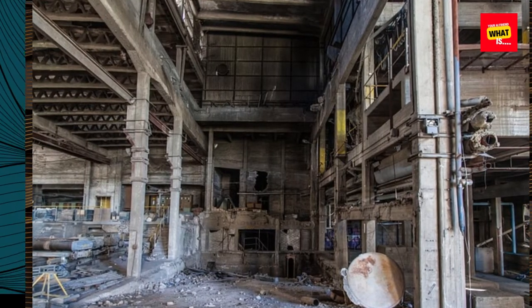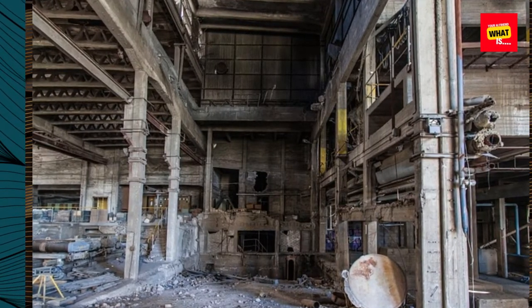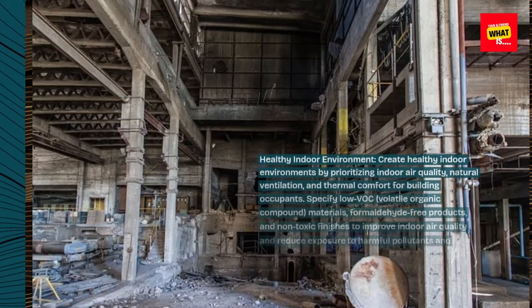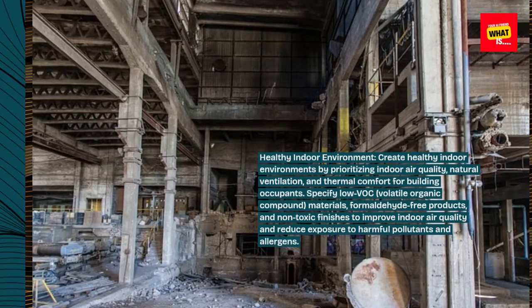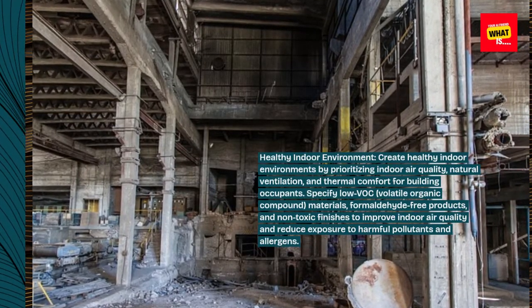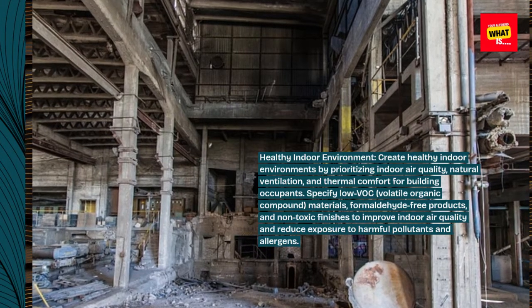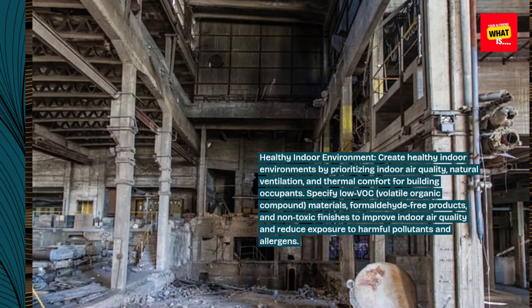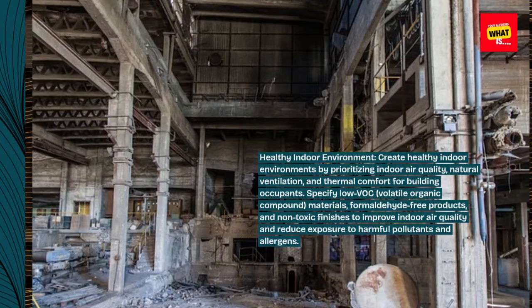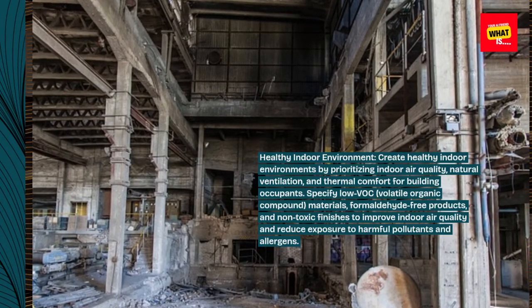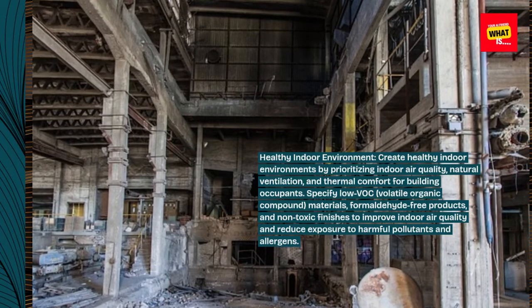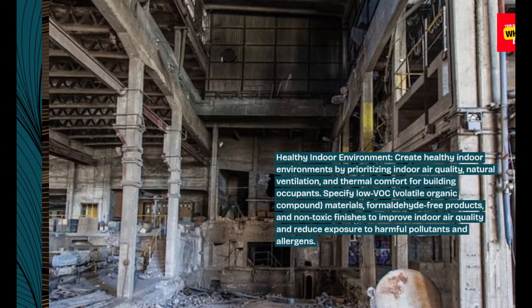Healthy indoor environment. Create healthy indoor environments by prioritizing indoor air quality, natural ventilation, and thermal comfort for building occupants. Specify low VOC, volatile organic compound, materials, formaldehyde-free products, and non-toxic finishes to improve indoor air quality and reduce exposure to harmful pollutants and allergens.